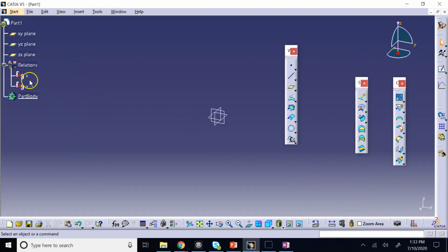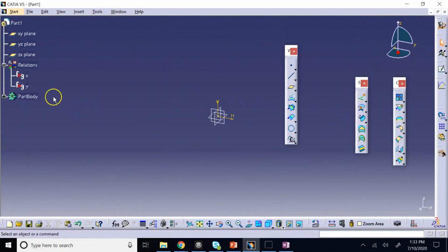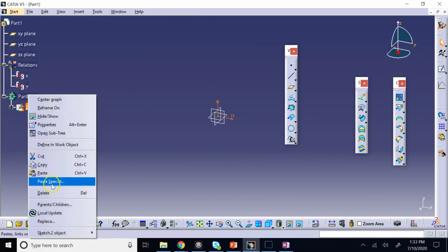And I get that. Now that I have it, I go to this plane, let's say, and I create a sketch. And here, when I click on the first point, you see this is the first point, right? And the coordinate of that is 0 and 0. Or if you don't want it even on the simple plane, you can do it in 3D. You don't have to do it in 2D, okay? So let me show you. As I said, you are not limited to any sketch plane.